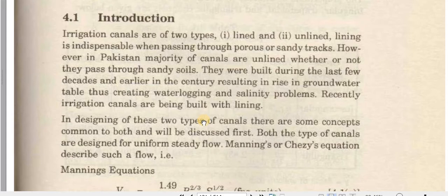Whenever we offtake a canal from the river or dam, our main target at the canal intake is always that the canal should offtake the maximum possible silt-free water. Simply, we can say there should be minimum entry of silt into the canals, and this is the main reason why we stop canal operations during floods due to heavy sedimentation.